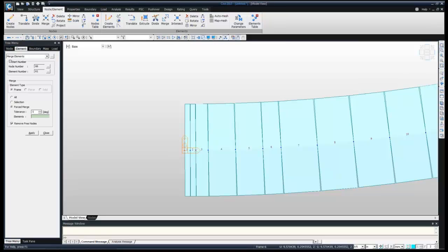Again, we can create one key segment from the wizard, which should have a length smaller than the previous segment and the segment after it. So the sixth, which is the key element, the key segment, should have a length smaller than the fifth and the seventh element according to the wizard. But here, as per this model, the key segment is bigger than that. So what we have done is we have included half of that part in the left segment, and then we're just going to merge both segments.